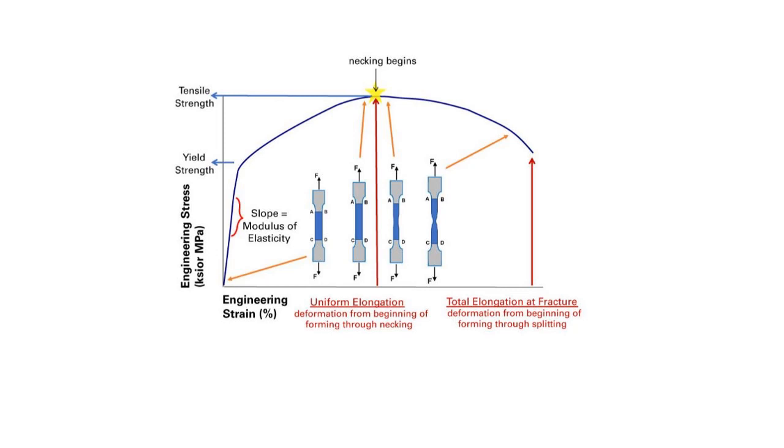Disadvantages. It does not provide information about the material at different temperatures. It does not identify the strength of the material at different strain rates. It does not identify any possible asymmetry in the material strength. It provides no information about the strength of the material in different environments. Since it is a destructive testing, the material gets wasted every time. The test is mainly for ductile material. It is done under constant strain rate and constant temperature.